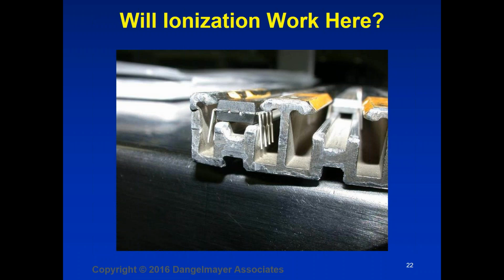So from what we talked about, does anybody think the ionizer will work in this application? Probably not. It's not going to do a very good job of removing charge from that package there because the IC package is surrounded by metal. So we would not expect the ionizer to work very well here. And, quite frankly, this is not what you want to do with your devices anyway. You have metal-to-metal contact here, and if there were any charge on the package of this device, there's a very good chance that a CDM ESD event is going to occur.